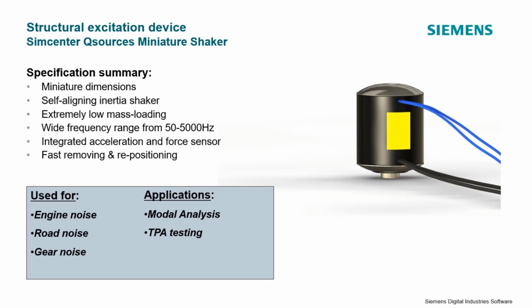When I've shown these to people who are very familiar with impact testing, they come to expect a certain amount of reproducibility or coherence at certain frequency ranges for their given structure. And these devices really allow you to set it up, put it on 500 averages, go to lunch, and you can come back, and with 500 averages, you can get an incredibly good coherence between your input and your response at frequencies you'd never expect, that are impossible with an impact hammer.